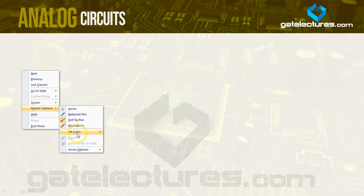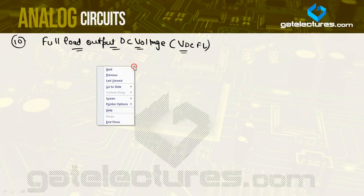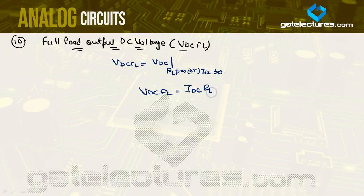Now let's discuss the 10th topic, which is the full load output DC voltage, VDC FL. VDC FL is the output voltage when RL is not equal to 0, neither is it equal to infinity, or we can say IDC is not equal to 0. So we get VDC FL is IDC into RL, and it is also equal to VDC NL minus IDC into